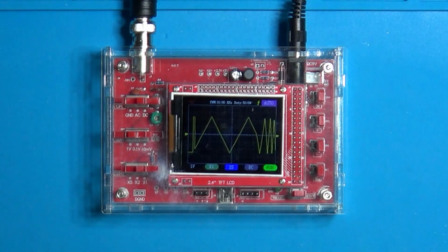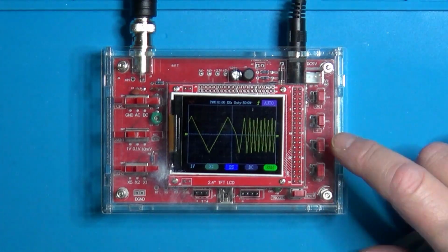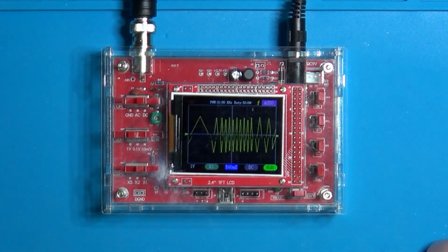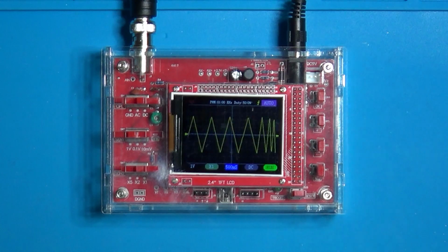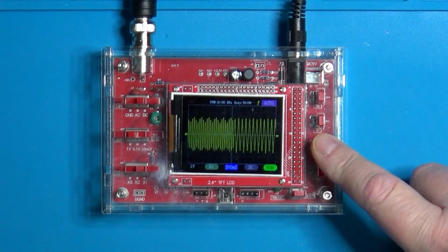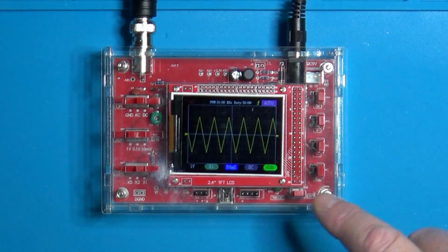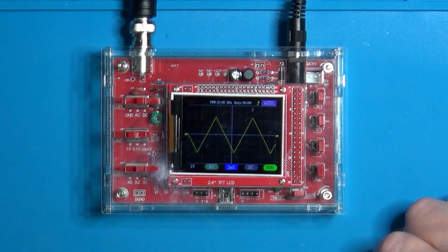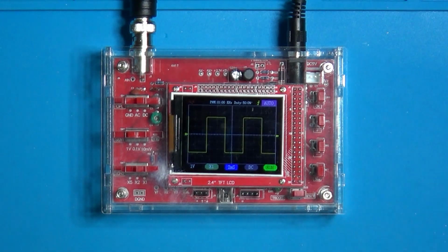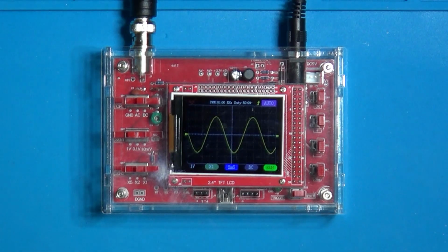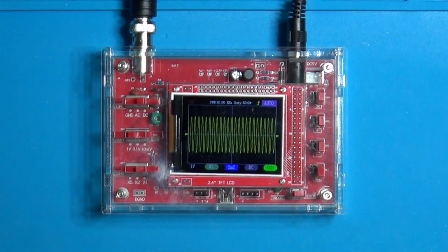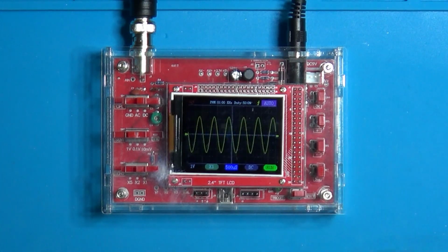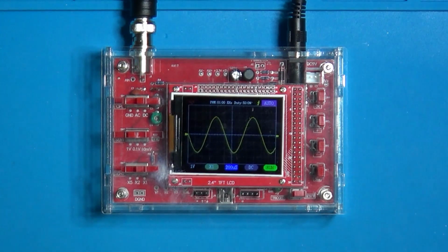Let's now go up with the frequency. This is now 1 Hz. Change the time base. Moving to 10 Hz and readjusting the time scale. Good. Going to 100 Hz. And it is perfect. And now let's try with the square wave. Good. And the sine wave. Very good. Moving now to 1 kHz. Adjusting the scale. The sine wave looks beautiful.